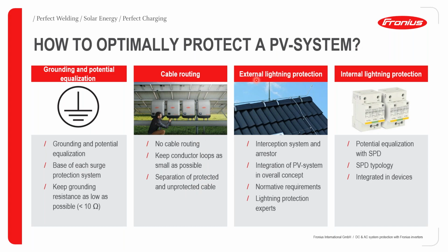You can also integrate external lightning protection. This will be like an interception system and arrest the lightning discharges. This can be integrated as an overall protection system for the PV system. And in some jurisdictions, this is a normative requirement.